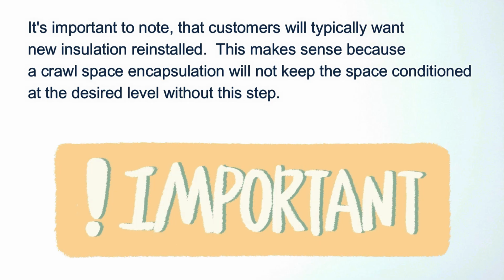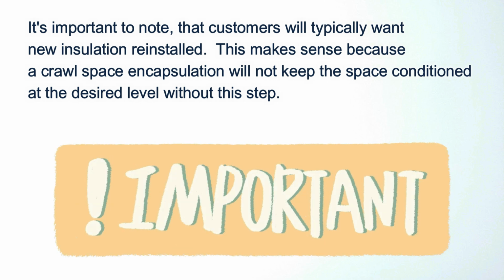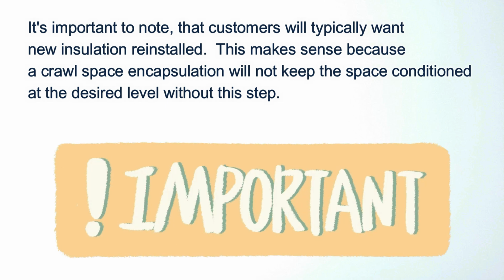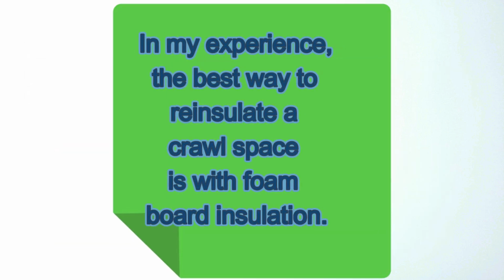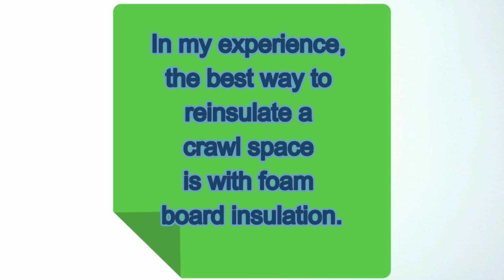Reinstalling insulation. It's important to note that customers will typically want new insulation reinstalled. This makes sense because a crawl space encapsulation will not keep the space conditioned at the desired level without this step. In my experience, the best way to re-insulate a crawl space is with foam board insulation.